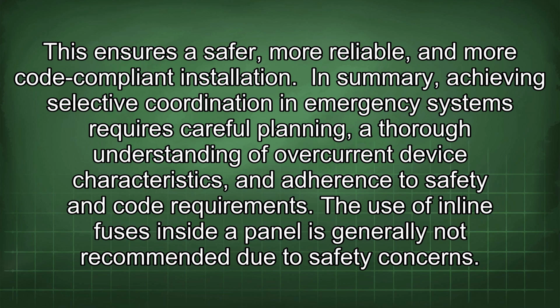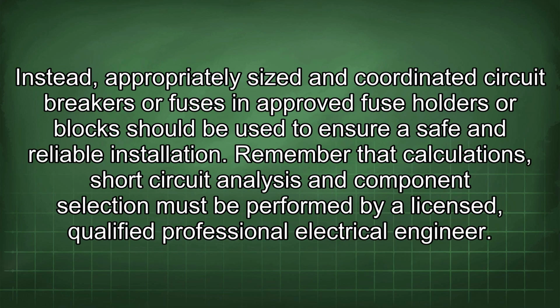In summary, achieving selective coordination in emergency systems requires careful planning, a thorough understanding of overcurrent device characteristics, and adherence to safety and code requirements. The use of inline fuses inside a panel is generally not recommended due to safety concerns. Instead, appropriately sized and coordinated circuit breakers or fuses in approved fuse holders or blocks should be used to ensure a safe and reliable installation.